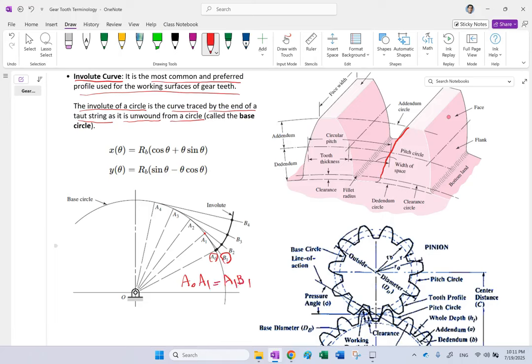That's the same rope. So you just open up that curve and make it straight. So this straight line is clearly perpendicular to the line OA1. It's a tangent line now. Then you move your pin point from A1 to A2, and this time all the rope that you had between A0 and A2, all this curve that was between A0 and A2, you open it up, make it tangent to the circle at point A2.